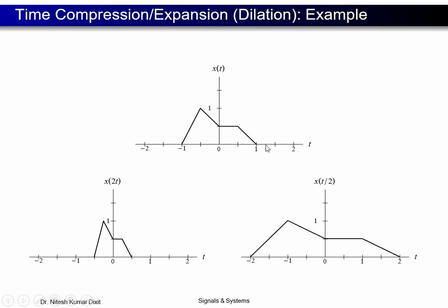If we scale t equal to 1 by 2, the new result of this point is 0.5. Here we do the same thing: -1 divided by 2 equals -0.5, but the amplitude does not change during the time scaling. So we get the new result here 0 to 0.5, and on the left-hand side 0 to -0.5. The amplitude remains the same.